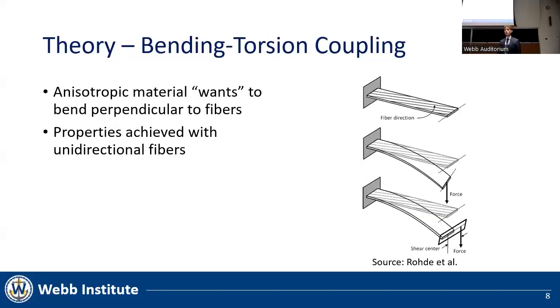While Pierce and Tennell achieved their bell-shaped lift distribution with a rigid twisted foil, this can also be achieved through bending torsion coupling. This is where the use of anisotropic material comes into play. While isotropic materials have the same physical properties in all directions, anisotropic materials can have very different physical properties depending on which direction you measure. In this case, highly anisotropic materials, such as unidirectional fiber composites, can cause intentional bending torsion coupling in the foil. The lift force acts on the foil like a cantilever beam, which generates the necessary bending moment for twist.